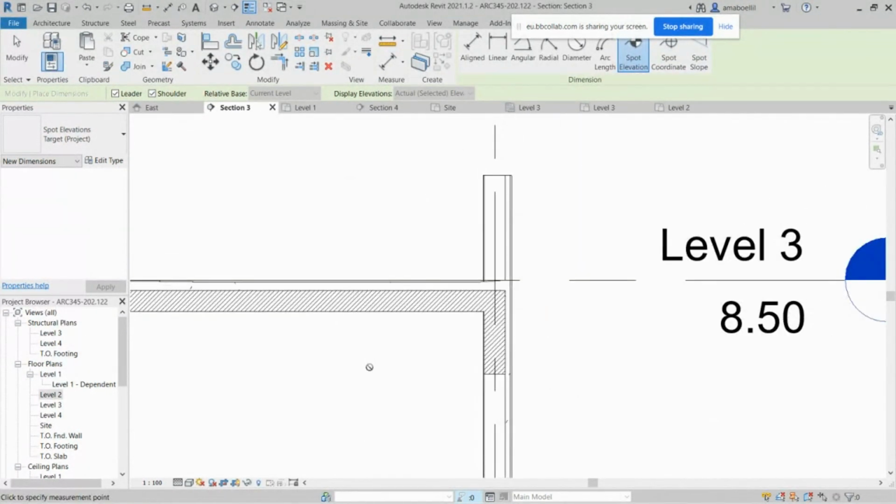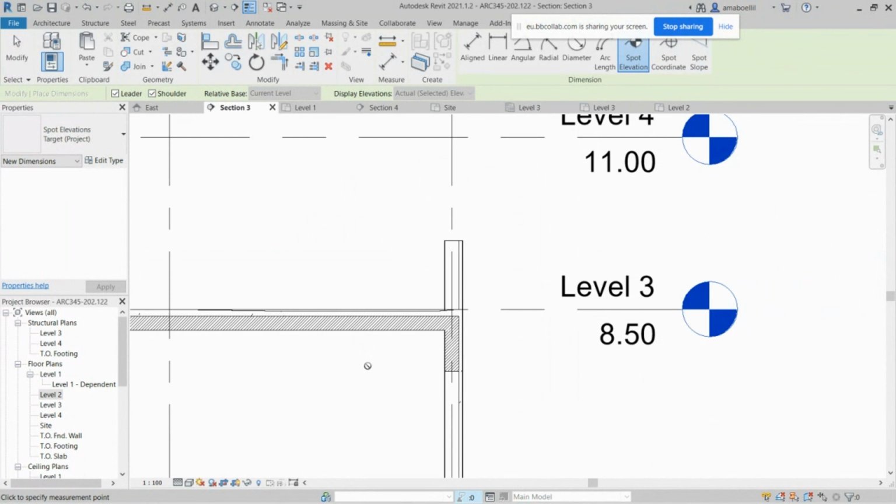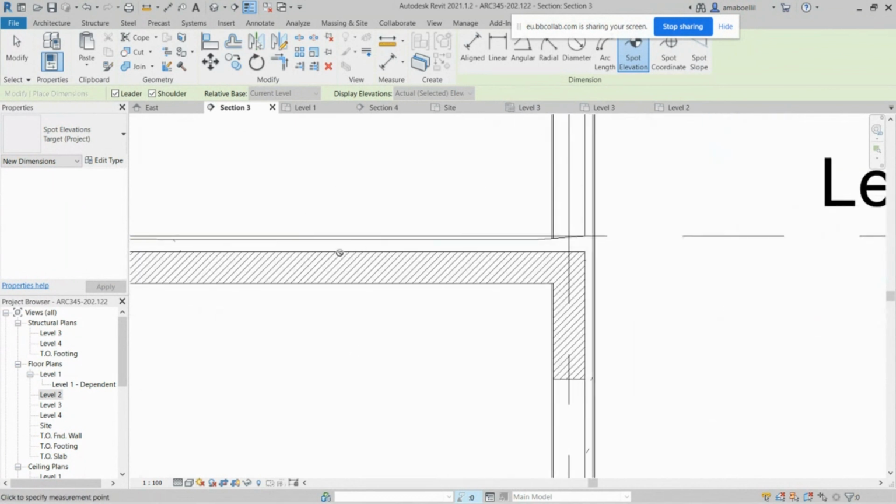Now, some schools say that when you refer to leveling the different stories that you have, you refer to the top of your concrete. Other schools say refer to the top of the finish. The top of the structural material is important sometimes, because that is the fixed one. Suppose you have some slopes similar to the roof, which level are you referring to? In other words, you might have here a level. If you go inside, you see the level changes here because I have a slope, so it does not recognize which one you're referring to.